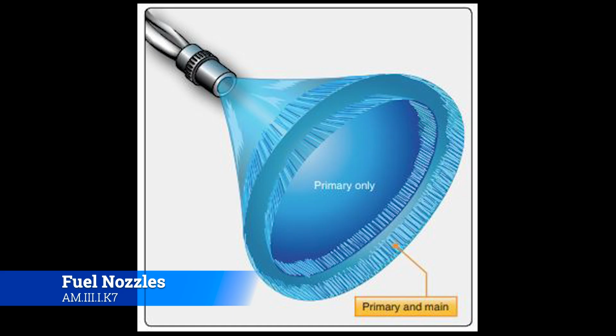A lot of times they'll tell you to soak it in fuel or some sort of solvent or cleaner or whatever. Some of the spray nozzles, they'll tell you never clean the face of it, because that could also cause damage to the spray nozzle. As the engine starts to burn, it burns a particular way. It has a certain soot pattern that comes up, and you don't want to change that. So really, this is a world where you have to follow the directions exactly, because these engines are very, very particular, and they're very, very expensive. And so if you make a mistake, it could be something that is very benign, very simple, but you could really derail a lot of things happening here.